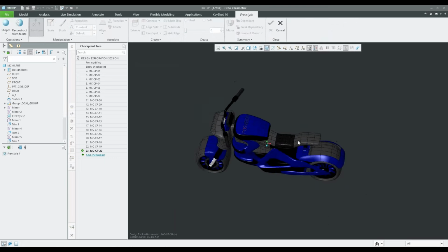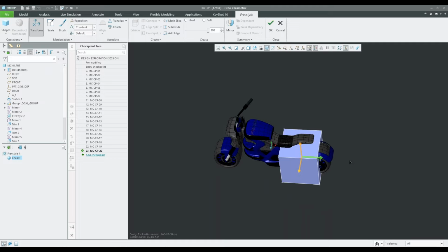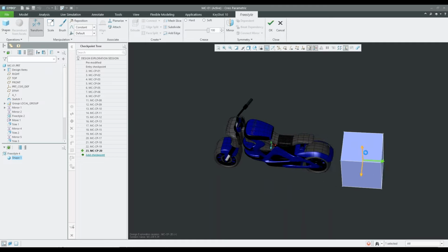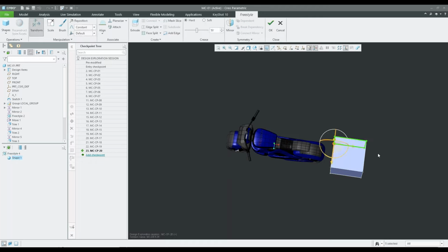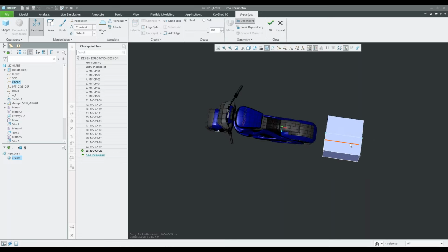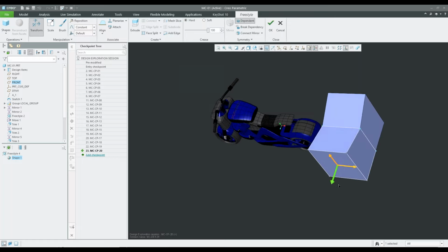All right, so previously, if I wanted to create a mirror, all I could do was, for example, if I created a cube, I could select these points, for example, and say, hey, I want to mirror about the front plane. Okay, and then whatever I did on this side, so if I grabbed an edge or a vertex or a face, if I sculpted on one side, right, we would get the mirror geometry on the opposite side, right?